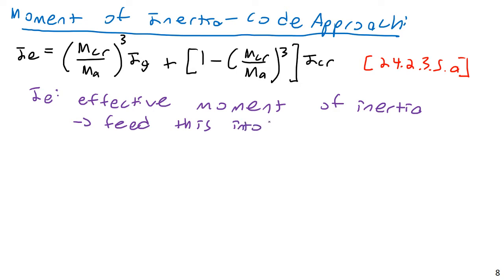Like what we saw previously, the deflection equation, I mean, the deflection of a distributed load on a simply supported beam, or the deflection caused by a single point load on a fixed beam. Any of those deflection equations. This is the moment of inertia you're actually going to use in your deflection equations. I_g is the gross moment of inertia, the moment of inertia of the gross concrete cross-section, as we discussed.